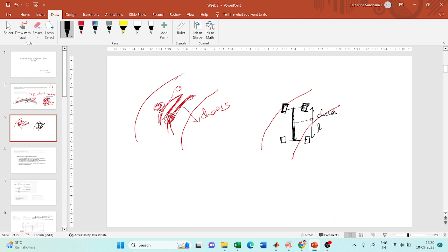Okay, if you see this vehicle, this wheel is thrown out, right? Yeah, this wheel is thrown out. So this much extra widening has to be provided. Now how will you find out this extra widening? So this is the extra width that is provided. Okay, so how will you find out this extra widening?